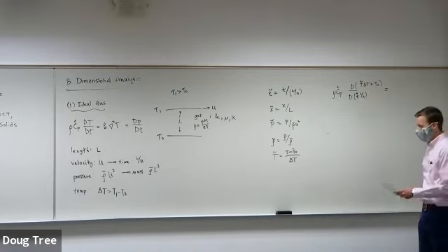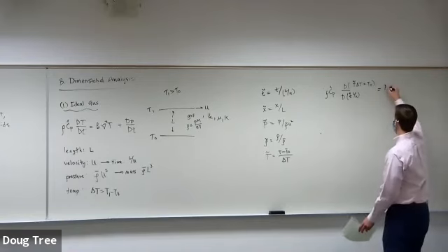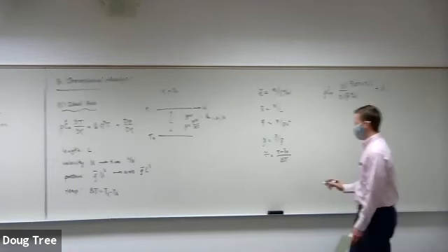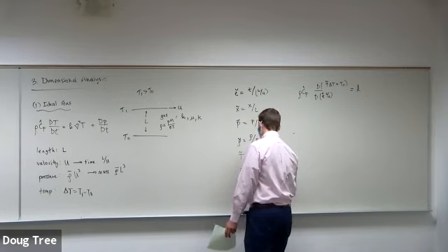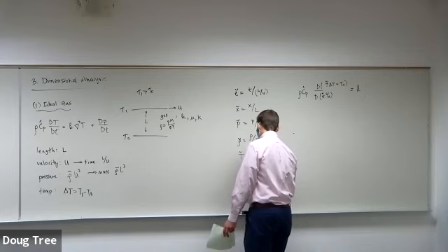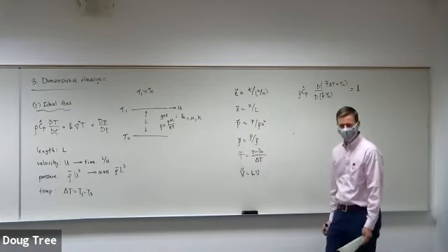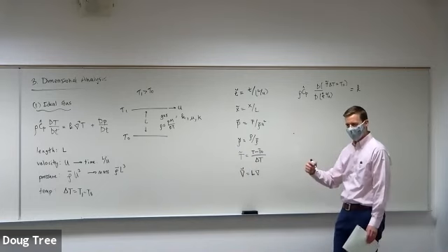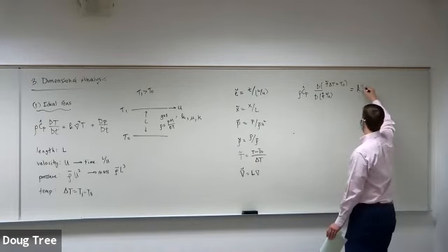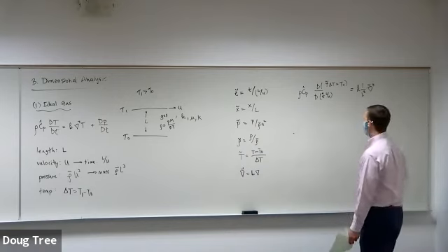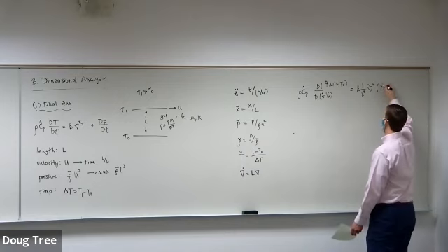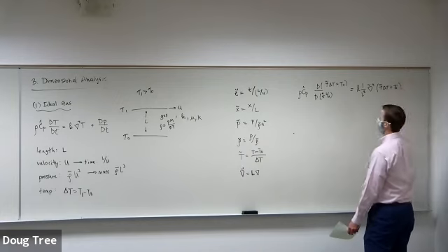Okay? And on the right-hand side, I have K. And remember that the grad operator is like L times the gradient operator, right? So grad squared is going to have an L squared. So this should have a 1 over L squared, grad squared T. And then again on T, I have T tilde delta T plus T naught.